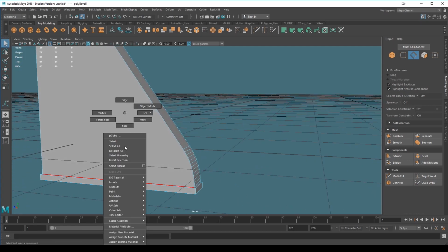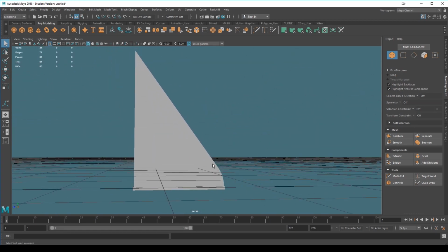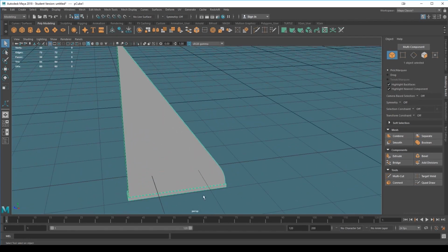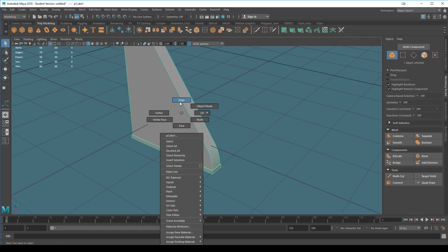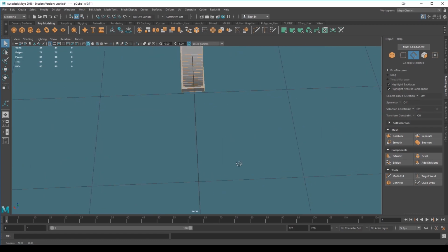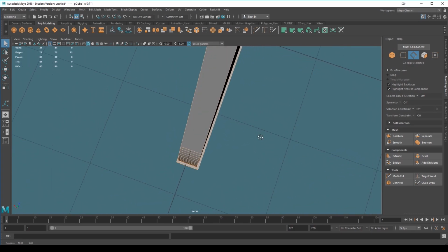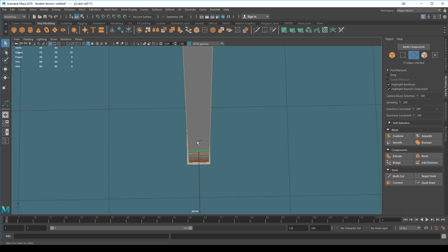So I just wanted to create a little bit more of an organic shape here at the bottom, but coming up to a pointy top. And now what I want to do is select all of the edges. I want to bevel everything except for those ones I've just made. So I'm just going to orbit, keeping it straight on so I'm not at a weird angle. What I want to do is deselect this section, so I'm just going to hold down Control, drag select through there.